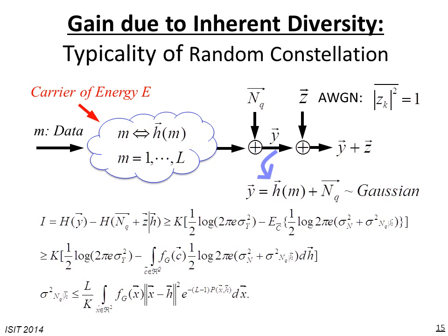To measure the degradation of this type of modulation with respect to what traditional random coding does, in which the constellations are selected independent of each other from transmission to transmission, and consequently the distribution at the channel input will be Gaussian, I am introducing some form of quantization with that vector NQ.